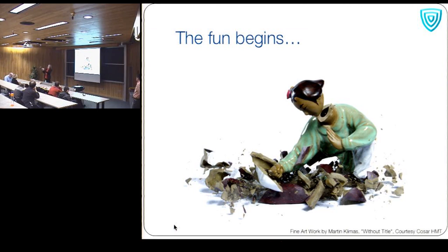So then you have other little cracks over here, and they start to grow, and this one starts to grow. So you excite the whole flaw population at high rates. And so that's why you get this more dispersed damage. So that's where the rate effect comes in: which parts of the flaw population actually exhibit damage. And it's exactly what we see.